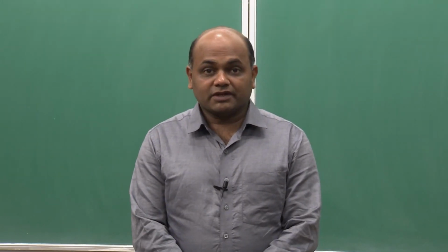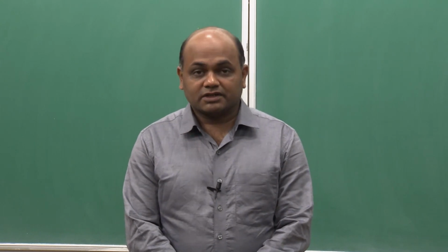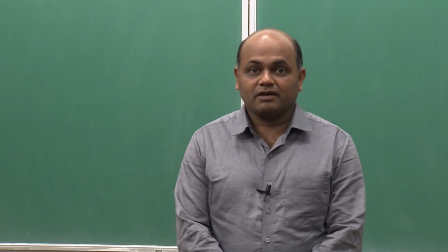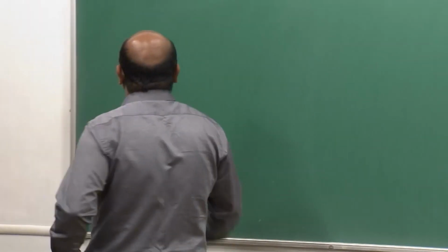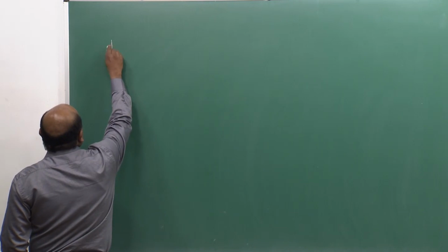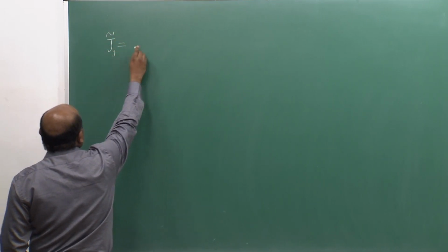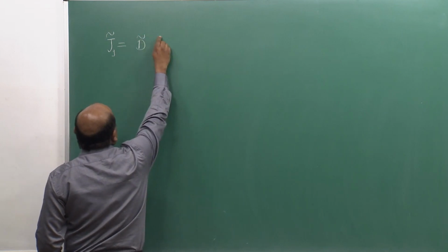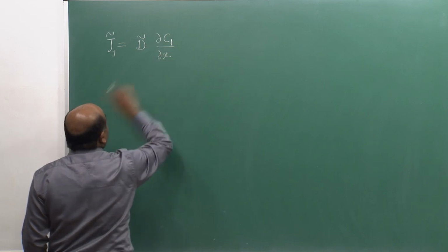We will first start with determination of fluxes, and hence the analysis of interdiffusion fluxes becomes very important. So, we have seen for binary it is very simple because there is only one interdiffusion coefficient that describes the interdiffusion flux of both the components.